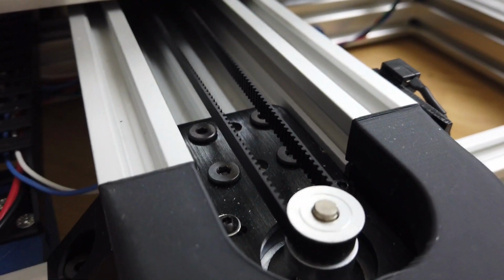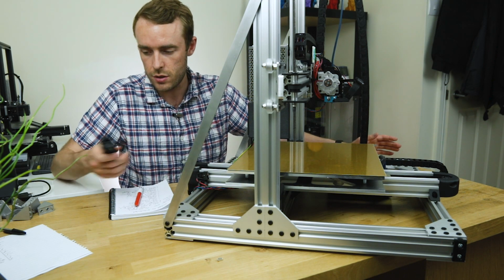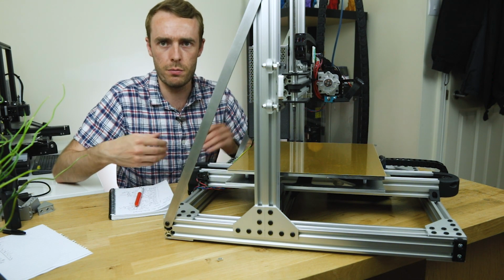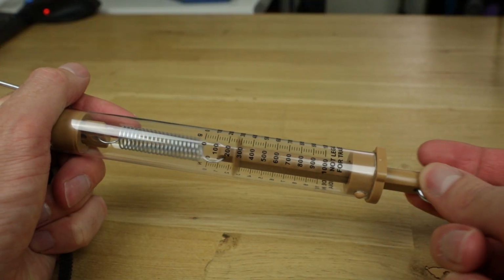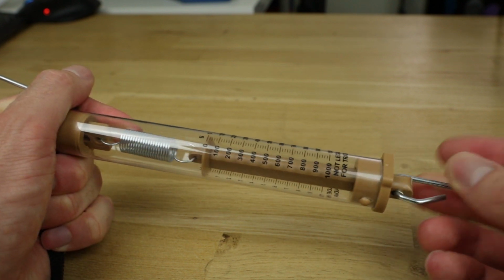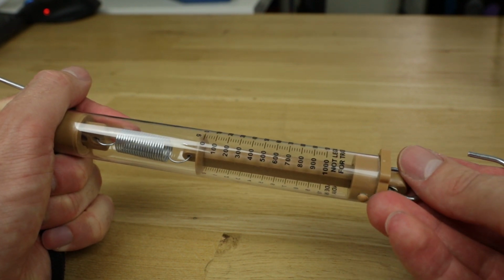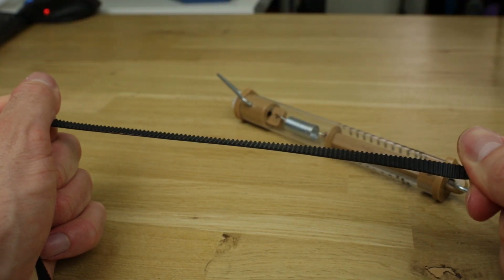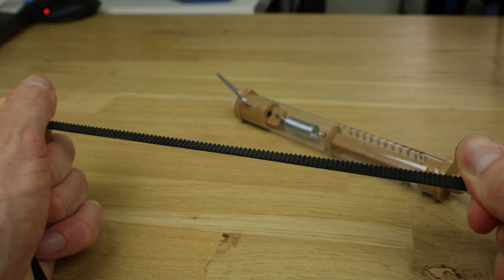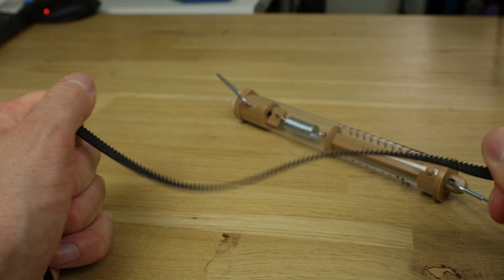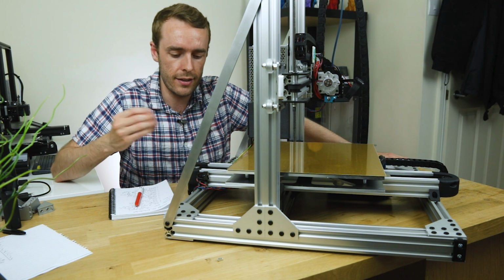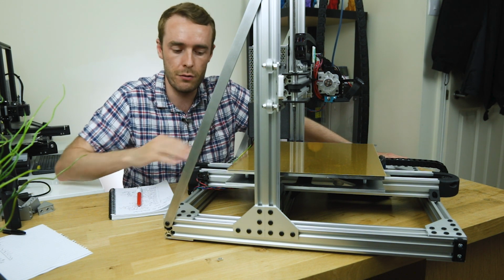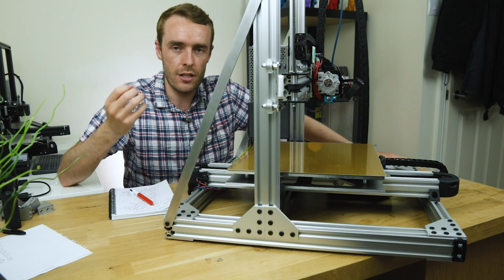The reason why this is not ideal is that in a belt, what you're trying to reduce is the amount of stretching. Stretching is obviously caused by the force. It's just like a spring. As you pull it, it stretches. The belt is no different. It feels obviously very not stretchy. That's kind of the design of the belt, and why it has, I think, aramid fibers lengthways in the belt in order to prevent it from stretching, but it still has some stretch. So the thicker and wider you get your belt, the less likely you are to have problems with stretching for any given weight. The other factor of the belt is the size of the tooth profile.